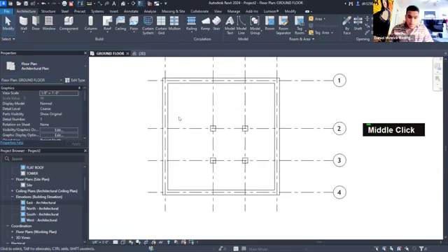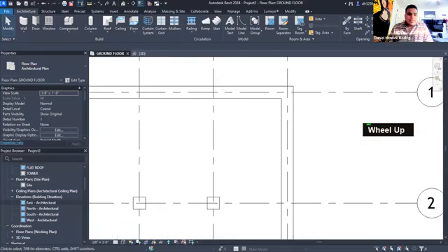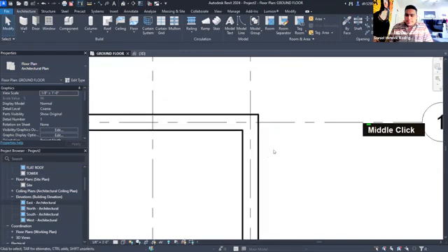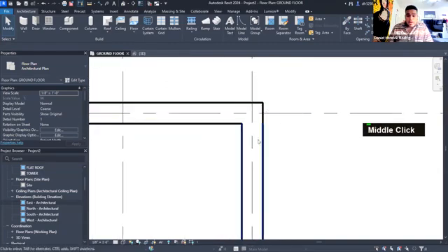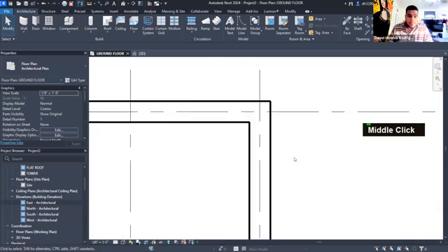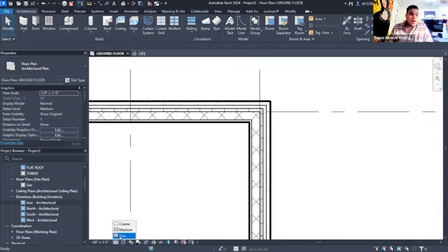And as of now, the walls just look like a mass, right? They just look like one large rectangle and doesn't really mean much. We're gonna come down here and we're gonna change our detail level from coarse to medium. You can use fine. I recommend fine for when you're taking a screenshot or making an actual sheet showing anything that has more details, or you can just put it in fine whenever you're doing sheets.